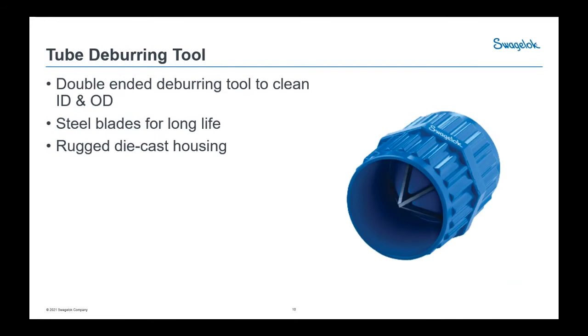During the cutting process, the tube cutters push burrs into the ID of the tube, and hacksaws are going to burr both the ID and the OD of the tube. But regardless of which method is used to cut the tube, these burrs have to be removed. Deburring is important for proper fitting function as well as for clean, leak-free systems. ID burrs can break off and cause damage to components and other parts of the system by lodging in the small holes or vents, or by scratching valve seats or soft seals such as O-rings.